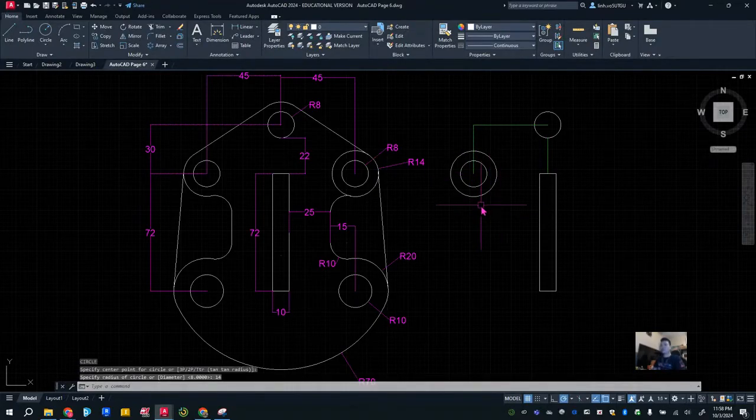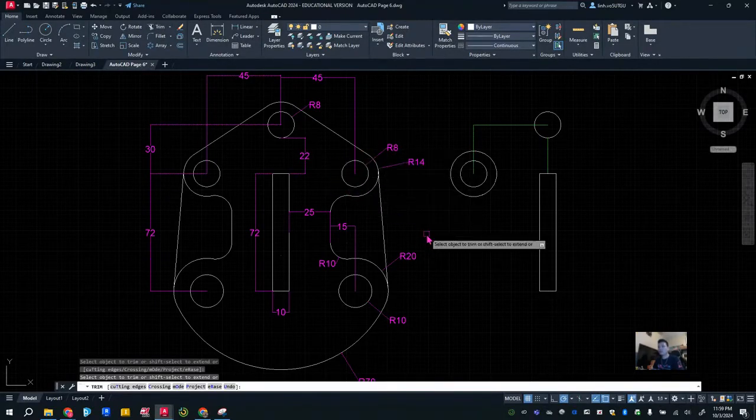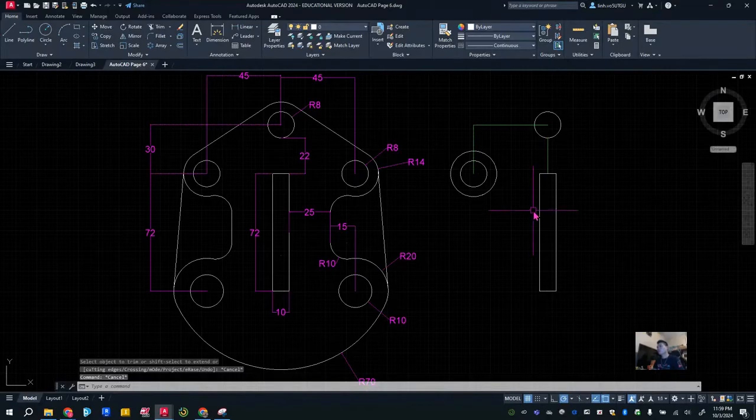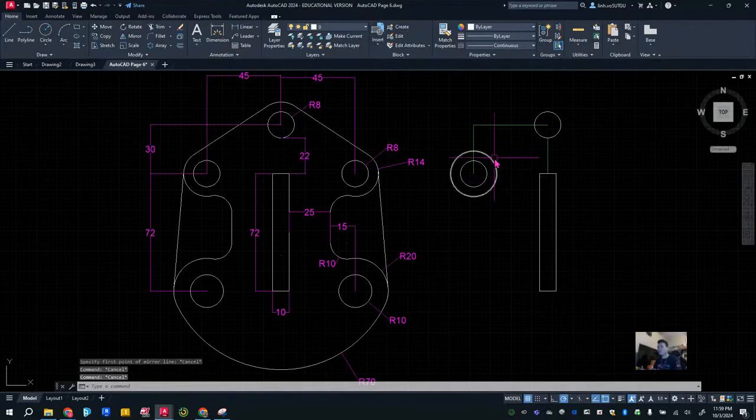All right. So when that is done, we can mirror that over to the right. It looks like this one's supposed to be trimmed right here. I forgot to trim that from the actual drawing. So I think that's supposed to be that way. All right, so now that is that. What we're going to do is take mirror. I'm going to select this option here, hit enter, and I can skip that real quick.